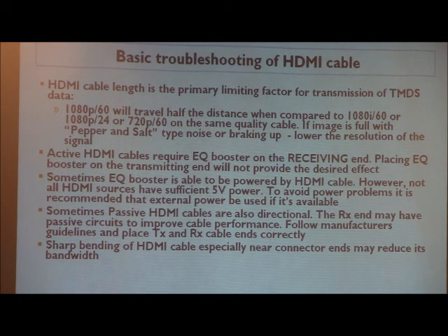Then you have to take some measures, because pepper and salt means you're close to the cliff, and with some changes in environment, humidity, and mechanical vibration, the connection could get worse and you can quickly fall over. So in that case, you have to do something. Maybe you have to lower the resolution to 1080i and jump back from the cliff. Maybe you need to shorten the length of the cable, or use a better cable that has more bandwidth and less shielding. It gives you a little bit better performance. So that's a couple of practical suggestions.